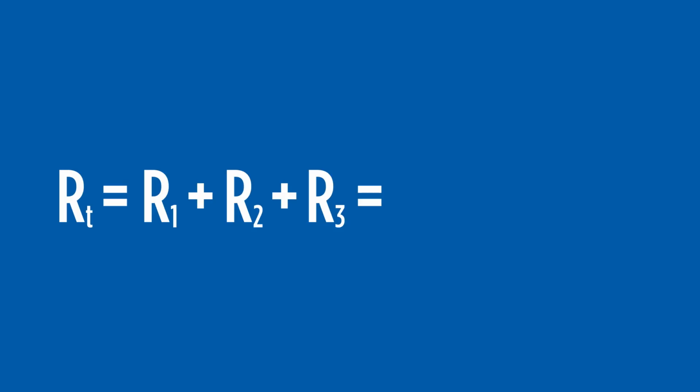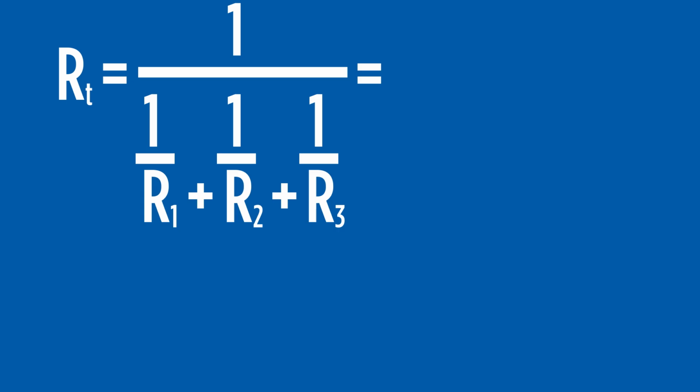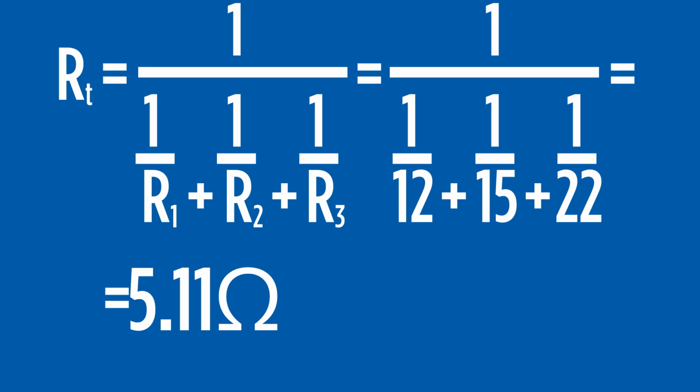Let's look at the calculation for each circuit, using the identical three resistors in both cases. We note that in the series connected circuit, the supply delivers current based on 49 ohms of resistance. The parallel circuit, using the identical three resistors, produces a load of 5.11 ohms. The calculations align with the observed operation in our analogue and the electric circuits, proving the outlined principles of both circuit configurations.